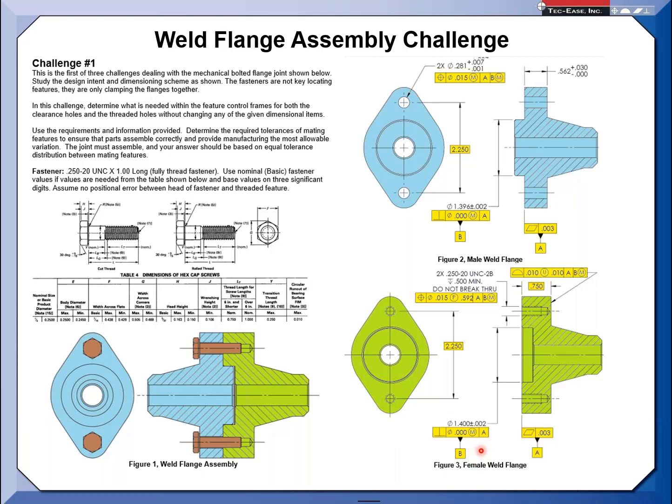Well, let me say this. There's not an example in the 14.5 where it's a secondary datum axis, which really winds up controlling location. In other words, this derives a datum axis that has an orientation to A. So there's no real location of this feature. Why? Because it becomes the primary locating datum. So depending upon what company you're at, the standard doesn't show any example where we put position in here. We consider this just an orientation control.